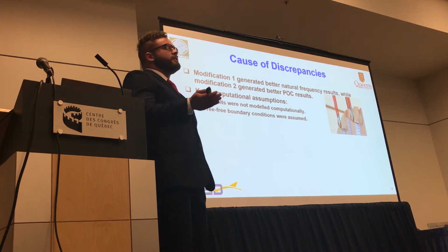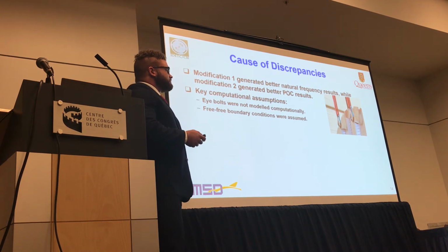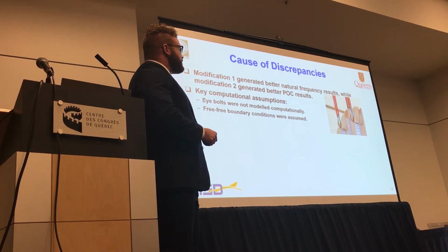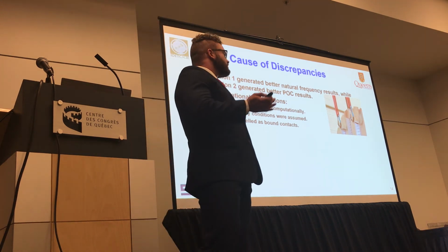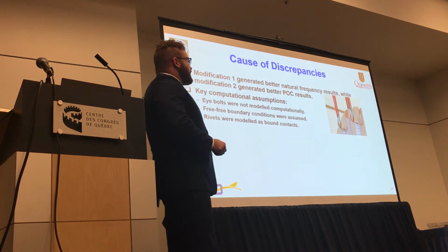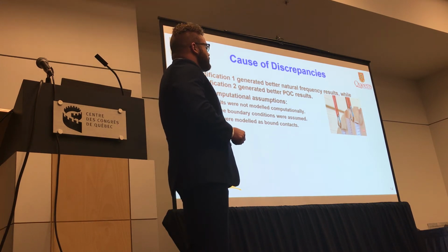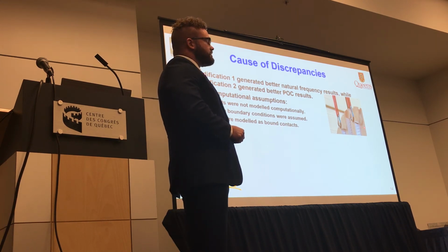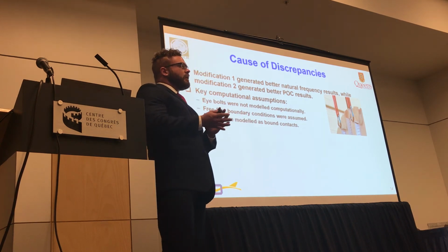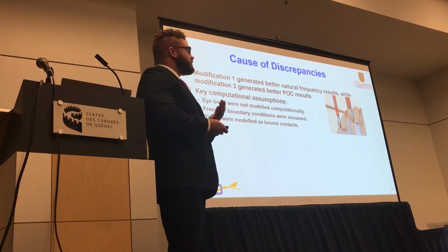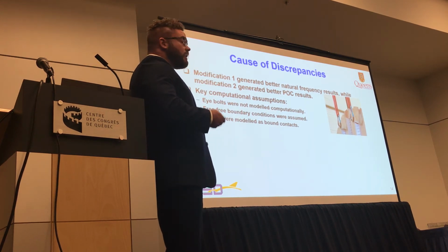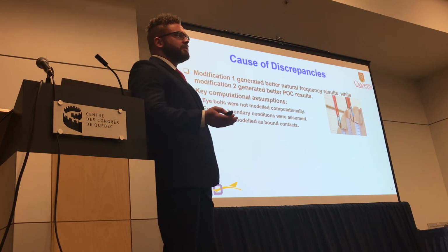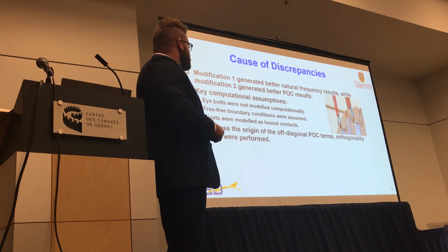And that was another huge limitation of this study: obviously there are going to be some constraints at this location of the bulkhead, which was not considered computationally. And then once again, the rivets were not considered computationally. If you look close enough, you can see there are small gaps here in between the stiffener and the plate, which is cause for coupling to occur between the stiffener and the plate of the bulkhead, which can shift some of these natural frequencies around and cause significant discrepancies between both the mode shapes and the natural frequency results.